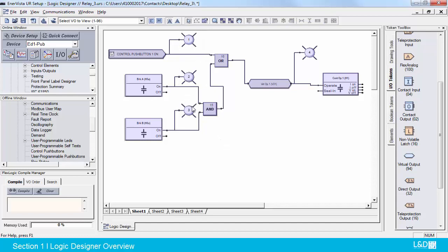Whatever is the last item you select will be the reference point for the alignment. So if I want to align the LED number 1 and number 4, if I want to align it to this height, then I will select this first, and number 1 second, and then I'll use the horizontal tool. You can see this now matches the same height as number 1. If I want to adjust the height of the virtual output, then I can also do the same thing. And the same thing here.